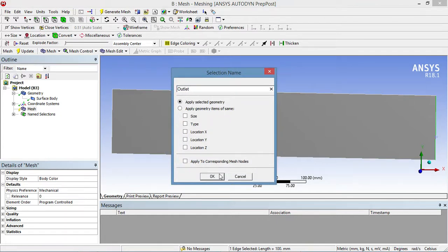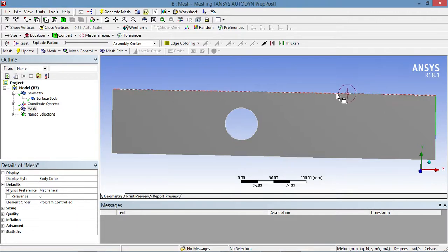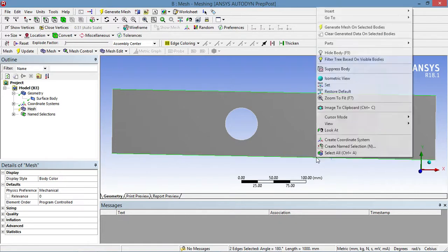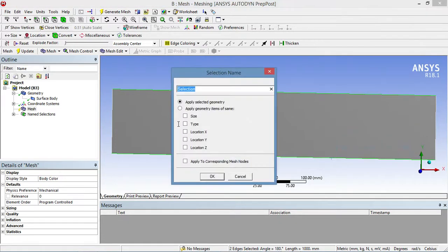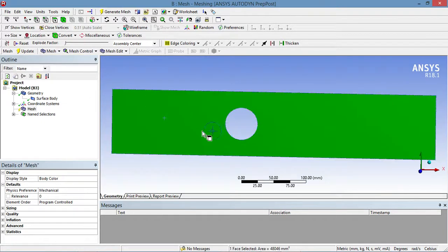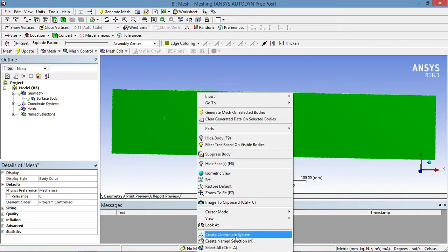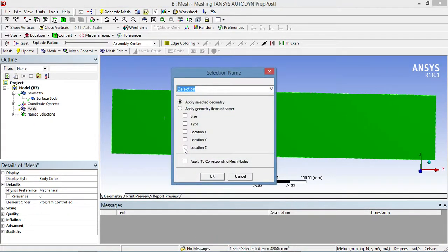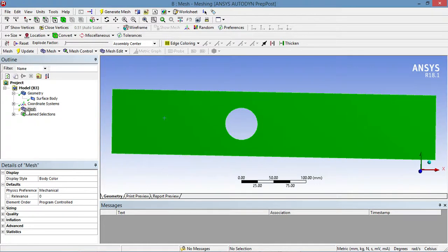The naming should be done because these are the things which will be accounted for in Fluent, which are the boundaries, the inlets and all, so that matters here. So this is my wall. Okay, done. So I think this is done, right? Pipe. And now I'll just choose the face, and I'll rename it as fluid. So there should be my fluid, right? That should flow. FLUID. Yes, my selections are done.